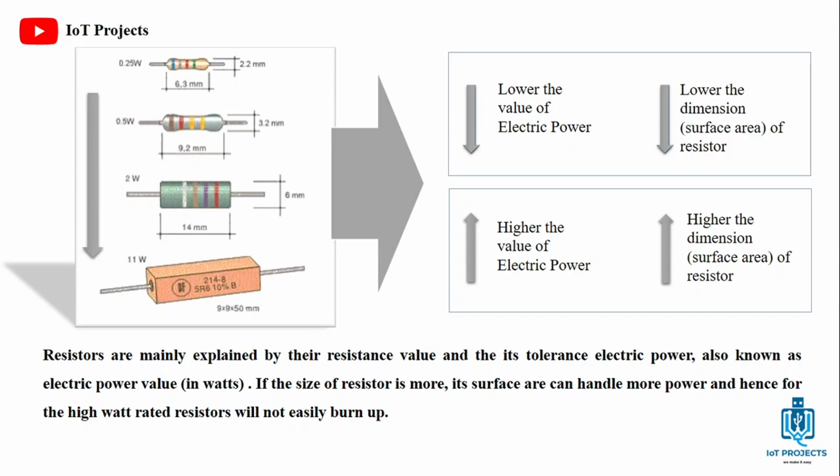The resistor wattage is how much power it can dissipate in free air when the resistor is 25 degrees above ambient. If you are not in free air, then you'll need to derate the resistor and/or live with a shorter lifespan and out of tolerance behavior caused by high temperatures. Depends what you are doing. If you are going to be dissipating more than 1/4 watt, you need to go with the bigger resistor. If it's under 1/4 watt, you can use that one.